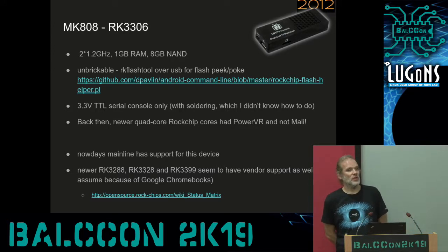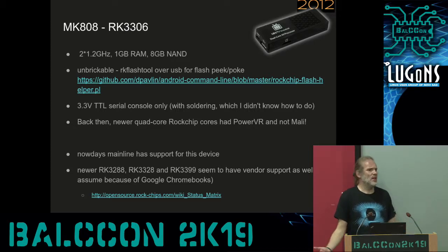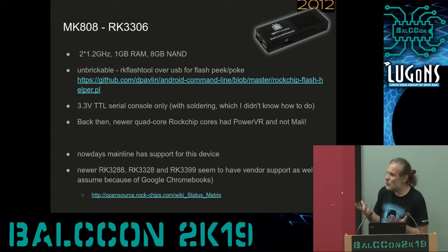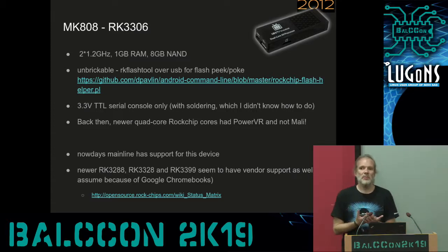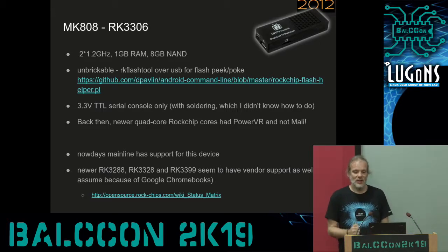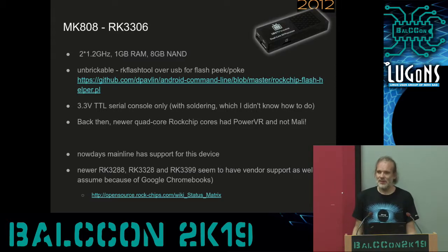You might ask the question, why would Rockchip do something like this? Because when they produced the dongles in the Chinese factory, they actually solder all the components on the board, but the board itself is empty. The NAND chip on the board doesn't have the operating system, so they do need some kind of mechanism to do the initial load. And we can use the same mechanism to actually take over control of the device.